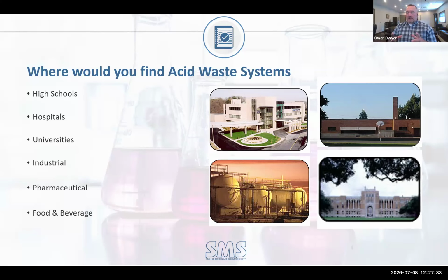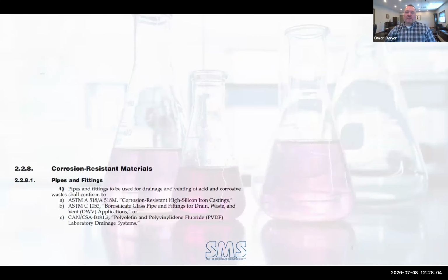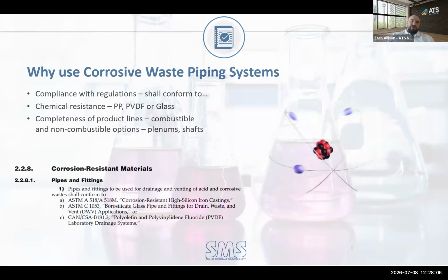So that stainless steel drain, for example, or the epoxy coated drain that you're going to specify should go into an appropriate piping certified system for that sulfuric acid, at that concentration, to a small neutralization tank that's buried in that area. And then anything downstream of that is now neutral. So you're now back to cast or copper or PVC or whatever your drainage system is at that point. But that's a good question to bring up. And in this particular application, it's a thing that you might not consider needing neutralization for.